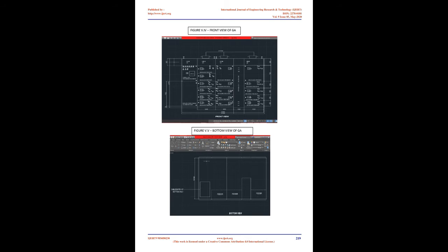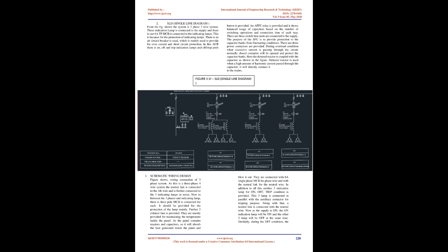For industrial purposes, to improve the power factor, an APFC panel is used, which includes a capacitor with the detuned reactor. It will maintain the power factor and maximize the receiving power. It contains an APFC relay, as shown in Figure 1. It is a microcontroller device which includes current control, voltage control sensor and many more. With the help of that, selection of capacitor will be done smoothly. Figure 1: Siemens APFC relay.